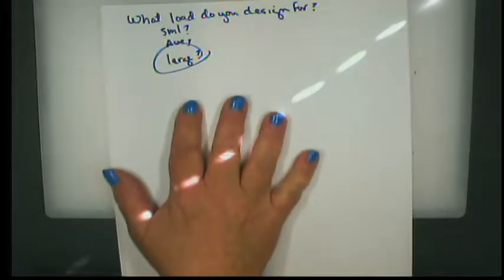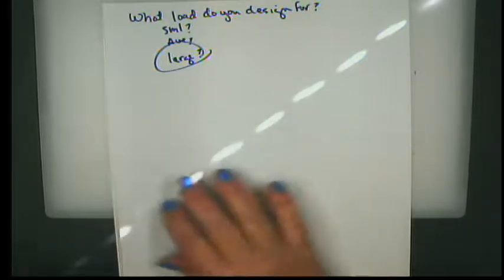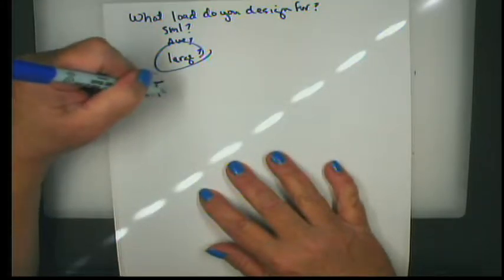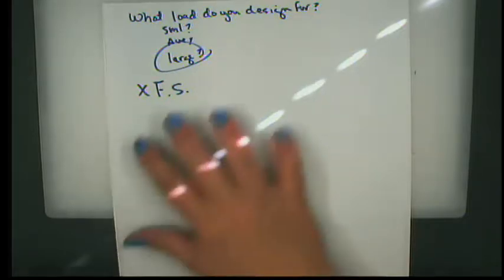So you want to design for the weakest part of the structure, the largest load, and then you include a factor of safety so that once you've thought of everything you can possibly think of and designed for the weakest link in the chain and the strongest pull on the weakest link in the chain, then you still want to gin it up because you want to make sure that it doesn't fail if there's a snowstorm and, you know, army troops marching on your roof and nuclear attacks and so forth.